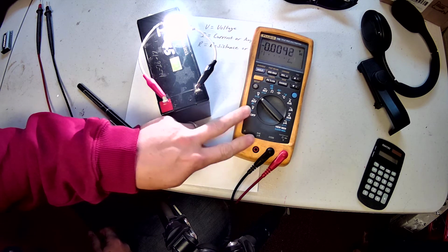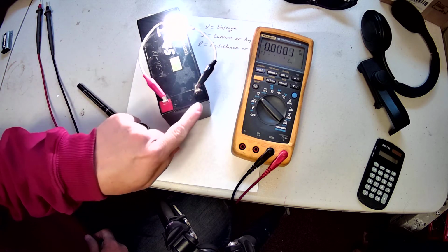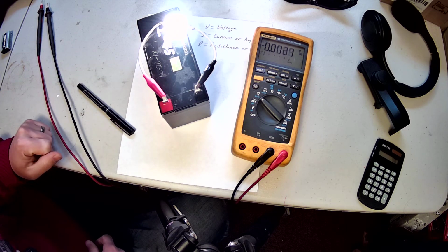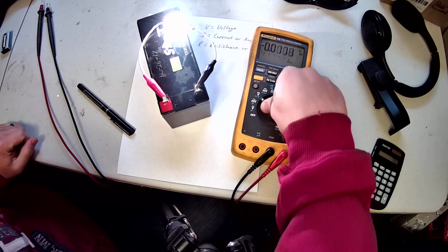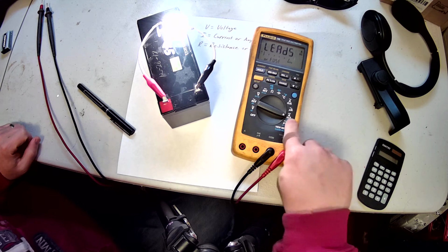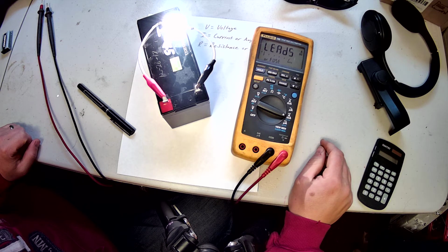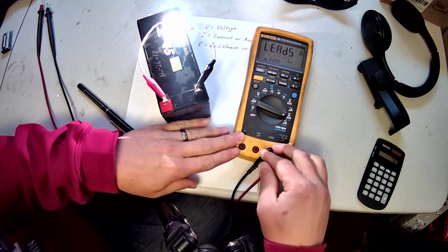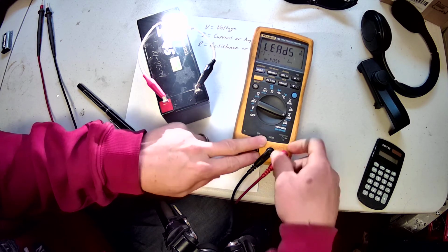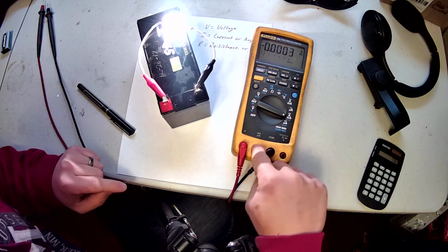But the problem is I can't use my meter on this right now because this is completing the circuit, which just means it's coming out of the positive and making its way back to the negative. I need to be able to get my meter hooked into that circuit in order to get a reading. So what I'm going to do is I'm going to put my meter to DC amperage, which is right here, amperage DC. But the problem is the leads need to be put in the correct location. If you were to test this without putting the leads in the correct location, you wouldn't get a reading, or you could possibly blow the fuse that's in the meter. So I'm going to go ahead, I'm going to take out the positive terminal and put it into where it says 10 amps max.